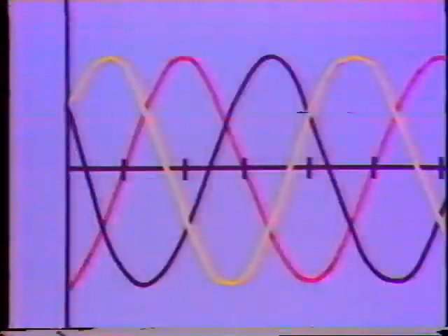The three windings are spaced exactly 120 degrees apart on the armature. So the sine waves occur at three different intervals, or phases. Everything occurs at three different times during one revolution of the rotor. Three-phase generators are used because they can produce more power than single-phase generators. The transmission lines that leave your plant carry three-phase power so that more power can be transmitted. And the larger, more powerful motors in the plant operate on three-phase voltage. We're going to look at motors later on, and you'll see what I mean.